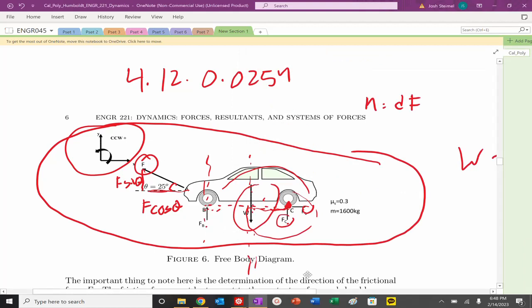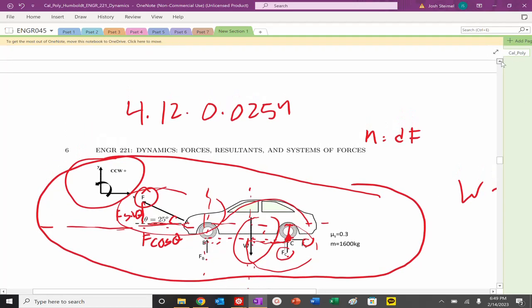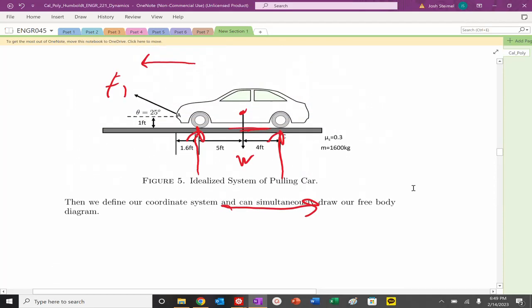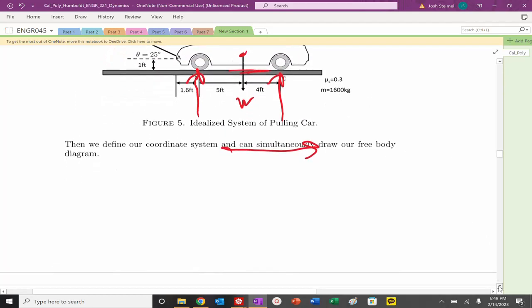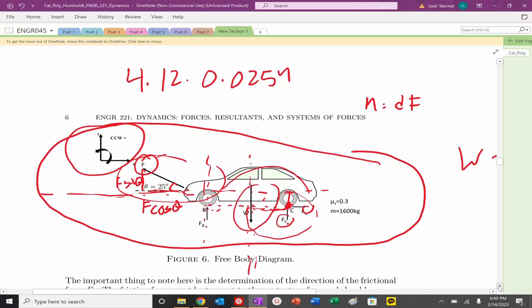Finished? Not quite, right? So let's look at what we have to consider as well. Let's first look at our cosine component, our x component. This is my line of action that goes through here. So the perpendicular distance is that distance above, which we were given to be 1 foot. Is this going to be a positive direction? Yep, I can curl around.